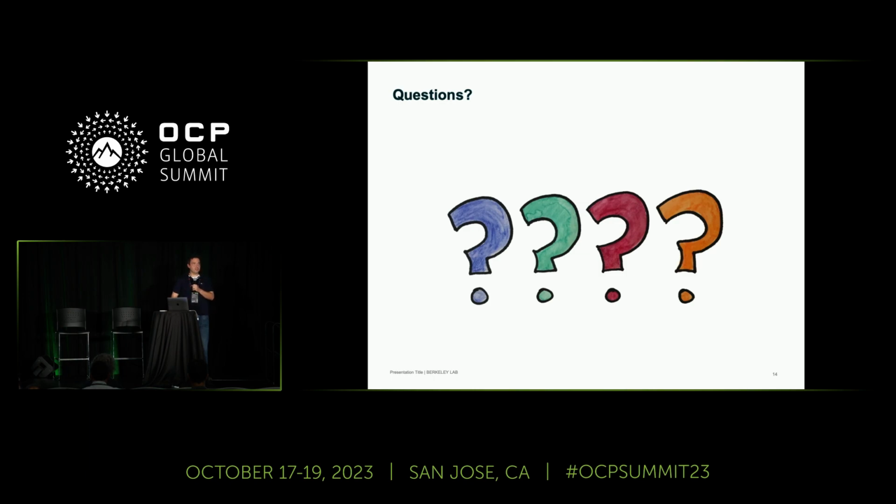Thank you for the talk. I have a question about the PHY. What kind of PHY are you targeting here? And what kind of FEC are you going to use? Because I see the latency requirement is pretty tight. Like the KP4 FEC we're familiar with is already like 20, 30, or 50, or if you include everything, it's already close to 40 nanoseconds.